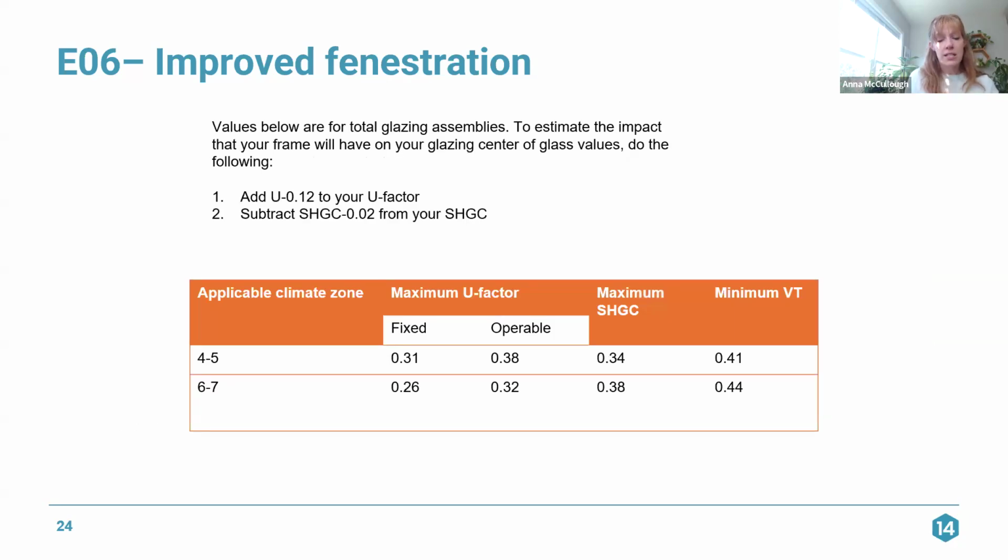I did want to mention that a lot of times we'll be talking to project teams and they will think that their glazing is better than what it is because they're looking at a center of glass value. So when we're talking about the energy code, we're talking about the entire glazing assembly, which includes the frame.